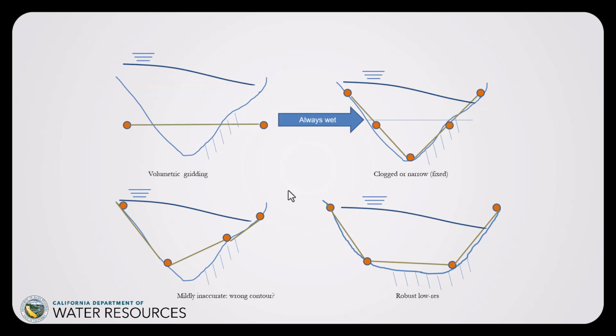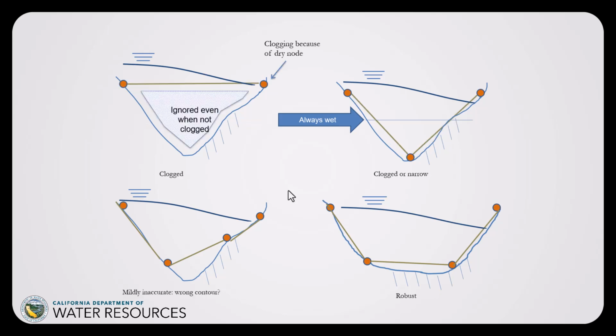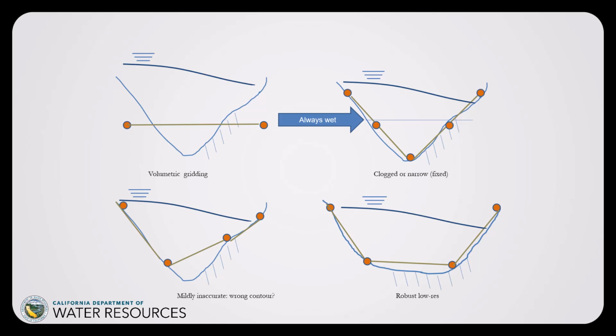We can layer in some fixes. In the top left, I moved the elements down so that they're at kind of an average depth for the whole cross section. So now it will have some conveyance. Obviously, it's a 1D representation, but SCHISM works pretty well in that capacity too. And then on the right, I've added a couple of extra nodes that mean that the sort of switching off that happens as we traverse the intertidal zone won't have as much of an effect on momentum.